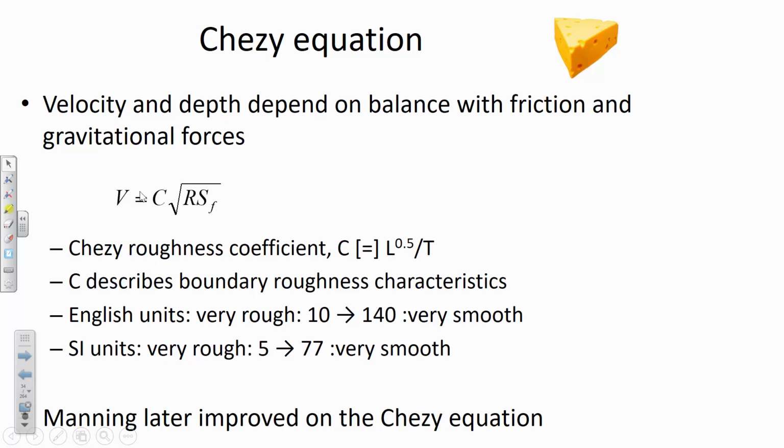And so there were these Chezy roughness coefficients that were developed, and the error that's built in to using the Chezy equation is pretty large, because in the same way that the Darcy-Weisbach equation does account for changes in flow conditions, you remember that the Hazen-Williams equation didn't last semester. You calculated some C value that was supposed to be constant regardless of what the flow rate was, regardless of the diameter, and so on.